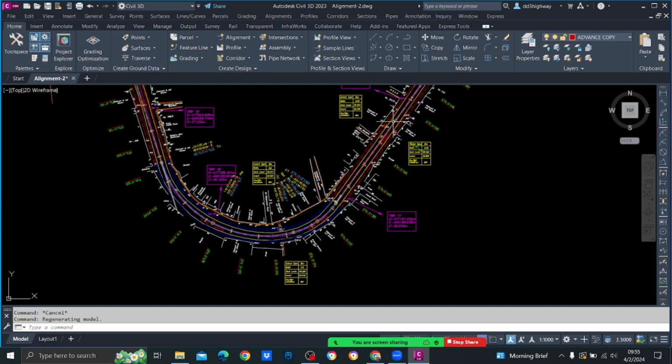Like that, in an assembly you have an assembly center line, then you take some components, called subassemblies, and make an assembly to match the typical cross section of this road. Okay, shall we start?